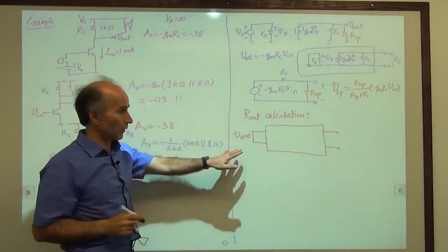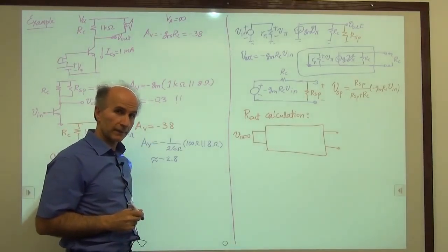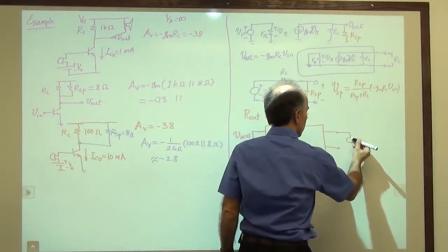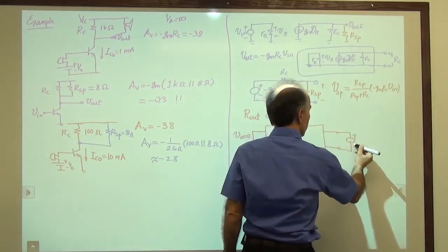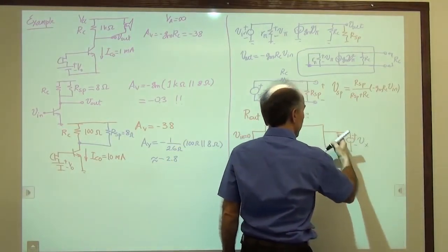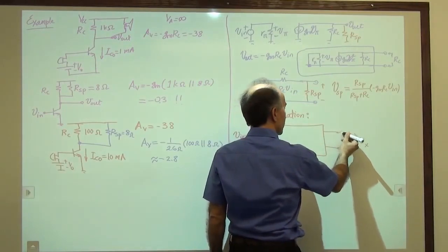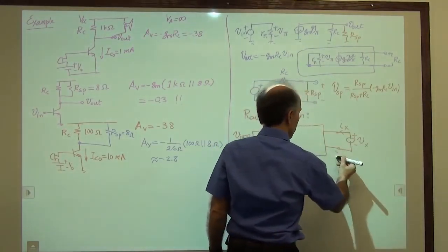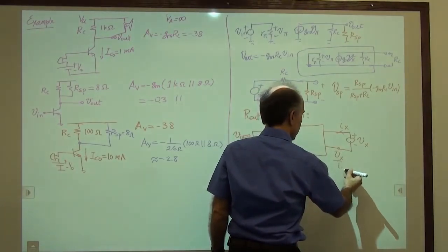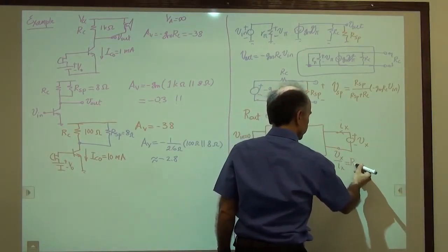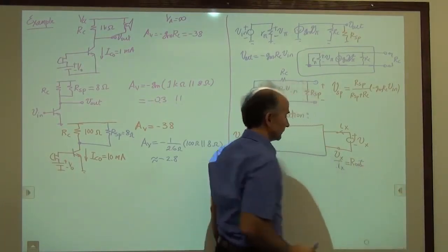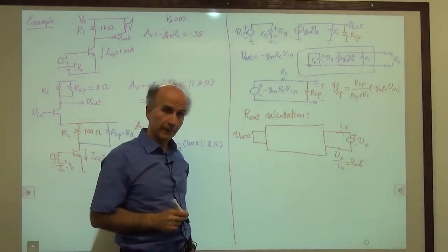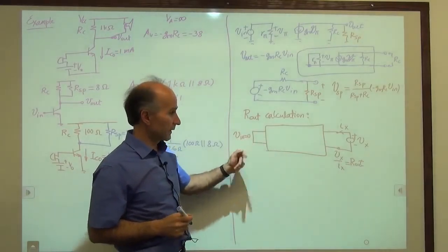All right, these are of course all small signal calculations. And then if you want to do it formally, we apply a voltage source, Vx, to the output nodes and measure the resulting current. And we say Vx over Ix is R out. So that is the output impedance, output resistance of the circuit when it's calculated under these conditions.